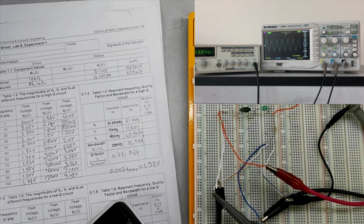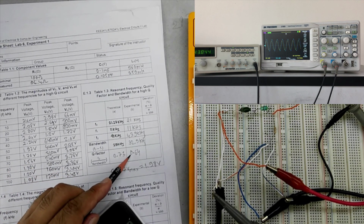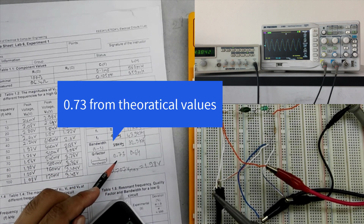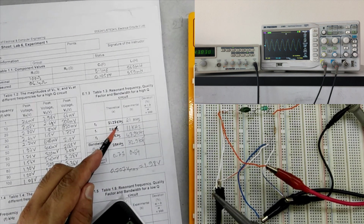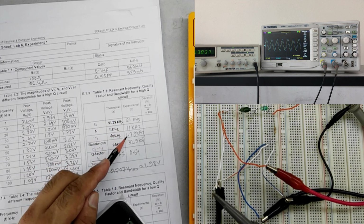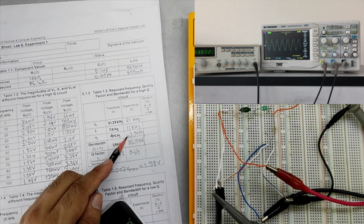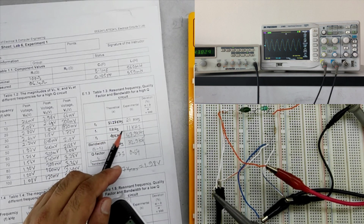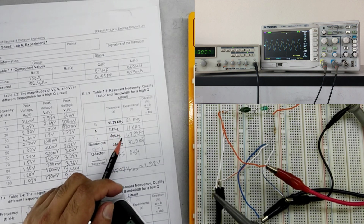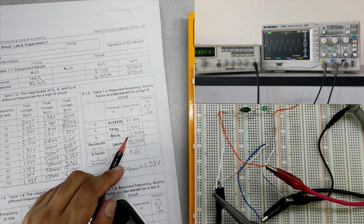So this circuit has a quality factor of 0.64 practically and 0.73 theoretically. The cutoff frequency is very close, 21 kilohertz. F1 is also equal, 11 kilohertz for both practical and theoretical calculations. However, F2 deviated a bit, from 40 kilohertz theoretically to 43.9 kilohertz experimentally.